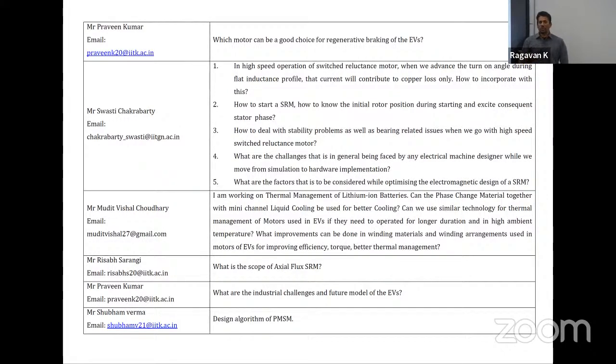A switch reluctance machine for a generator is fine, but I would not put it in the top 5 or top 2. So some version of PM assist motor, there are several topologies. PM assist alone, there's a slew. You have ferrite assist, you have neodymium assist. So one of them would be better suited, even if it's not a conventional IPM.